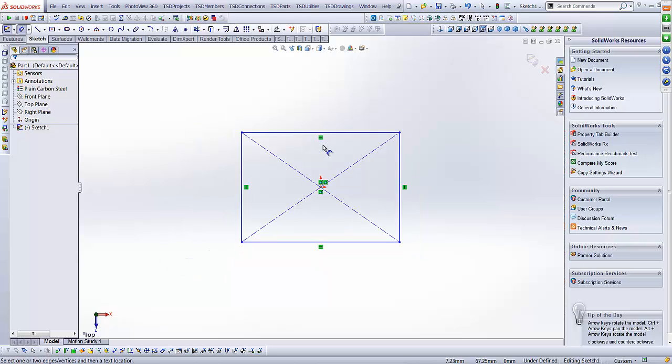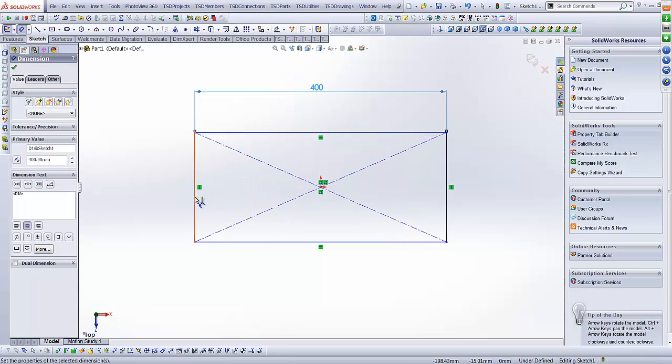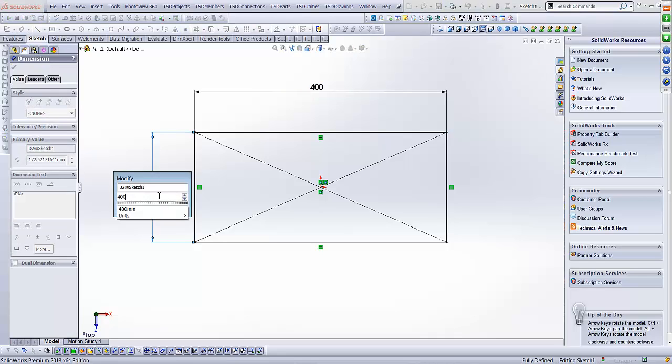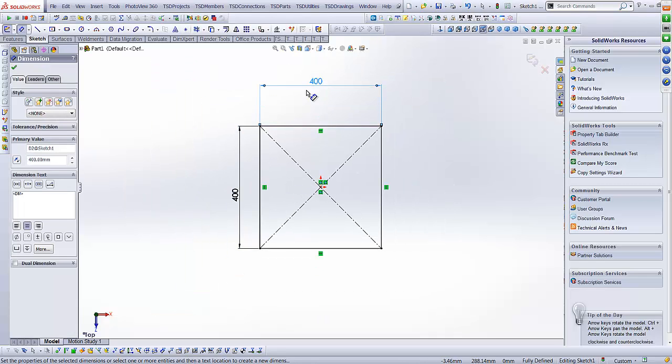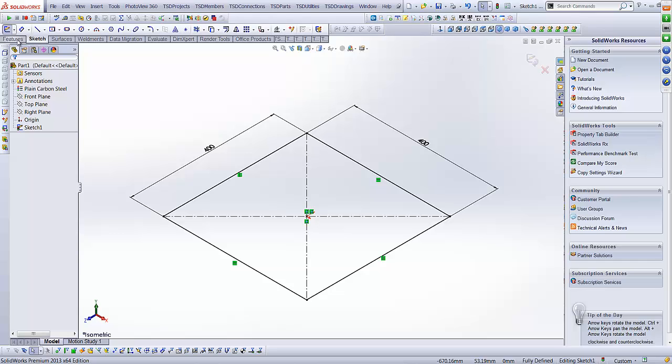Now I'm just going to set this up with some dimensions. I've just right mouse clicked there and selected the dimension across, and that allows me to start the process. So I'm just setting up some basic dimensions here. Now this plate, you could link the vertical and horizontal lines to make it so it's square, but I want it to grow in certain directions, so I've left it so I've got both open. Alright, so now that's just started my sketch, and now I'm going to extrude it.